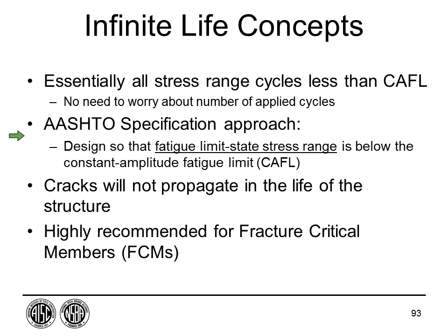Now, is this economical? Well, actually it's quite economical because the stresses are linear. So in other words, if I need to lower my stress by 10% or 15% to make it infinite, I simply need to add some more steel, make the girder a little deeper, but it's generally not difficult to improve the fatigue life. And always remember, the other way I can do this is simply use a more fatigue-resistant detail. So rather than have an abrupt termination, maybe I have a smooth termination. And now I have infinite life simply by changing the detail and nothing else.